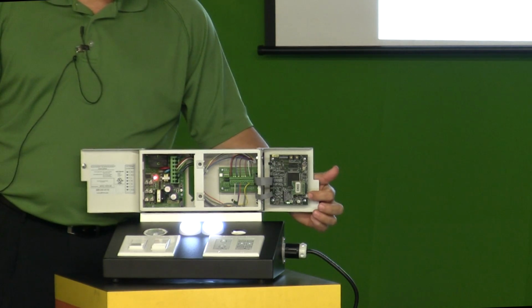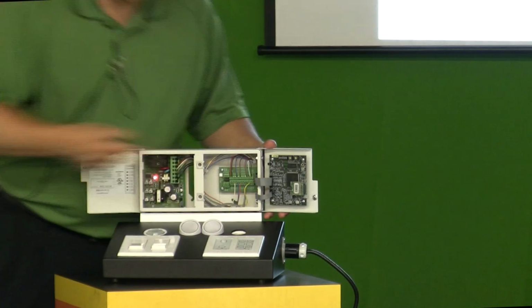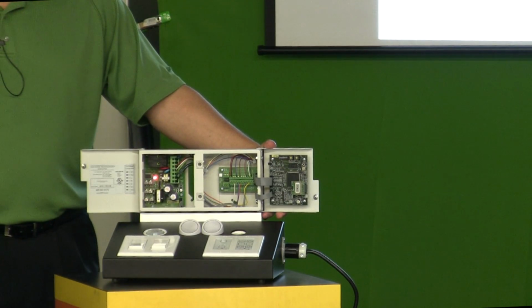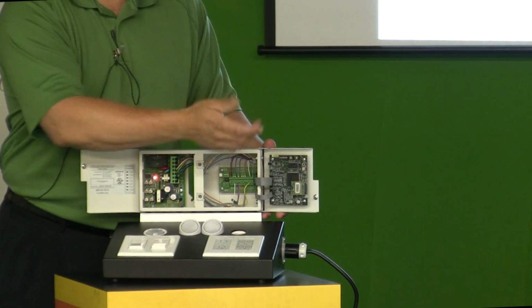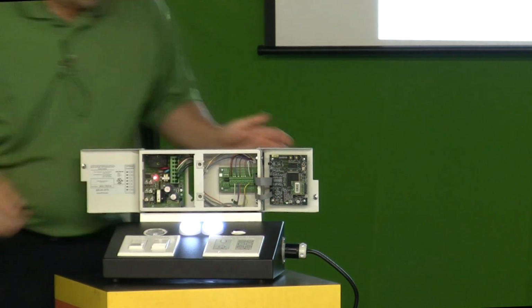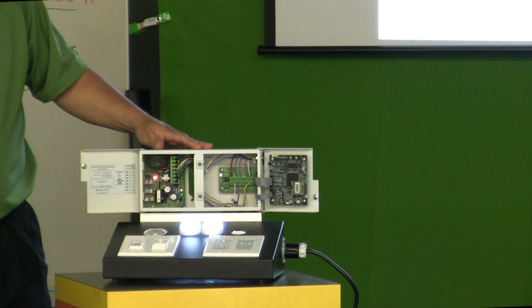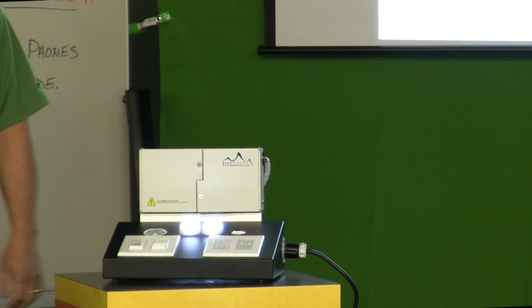This is the micro USB port right here. The controller board itself has a power cycle switch, so when you change DIP switch settings or MAC addresses, you typically have to power things down, and instead of having to go find the circuit breaker to do that, we just try to make it a little easier for you. So that's pretty much it in a nutshell for that little device.